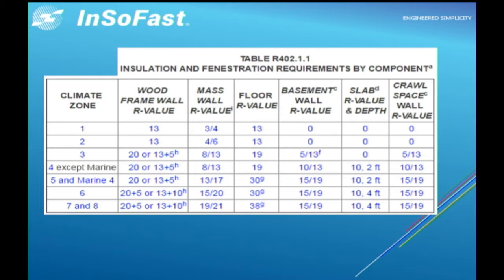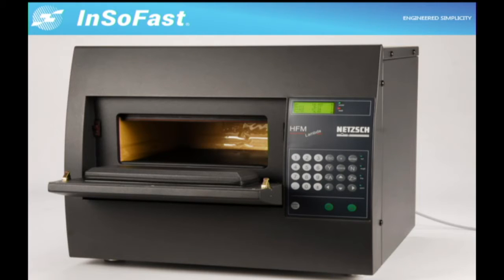So as we're looking at the insulation codes, what we're really going to be talking about today is the increased requirements for climate zones 4, 5, 6, 7, and 8. In particular, R-15 continuous. Now, again, R value is just a performance of the material.